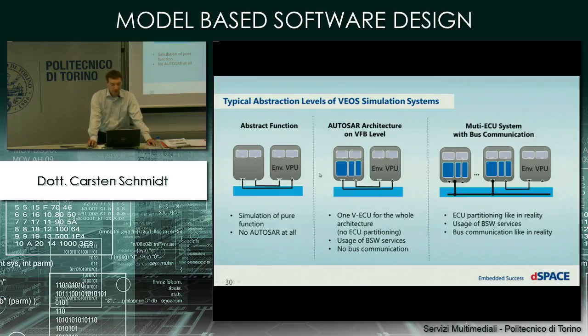So you would put all the software components of your architecture in one virtual ECU, and you would use the base software services, but you would not use them in a similar way as they would occur later, but you would generate an implementation that just works in this case.